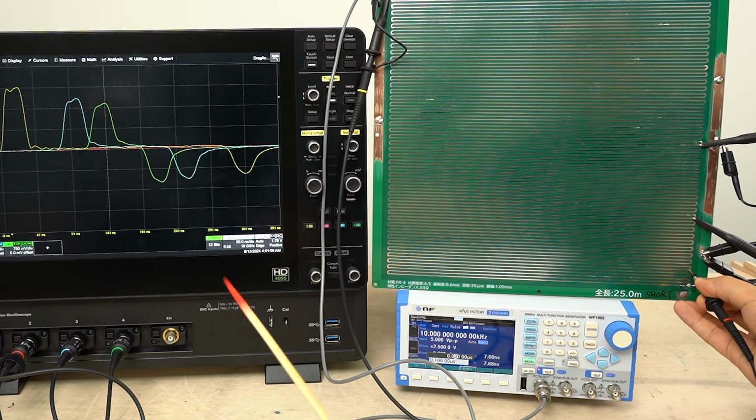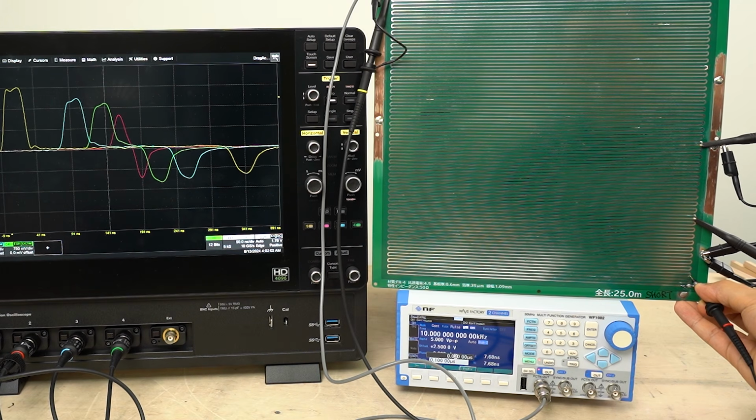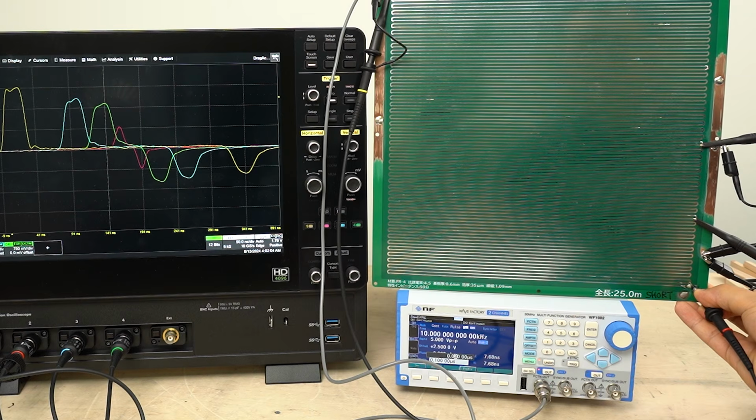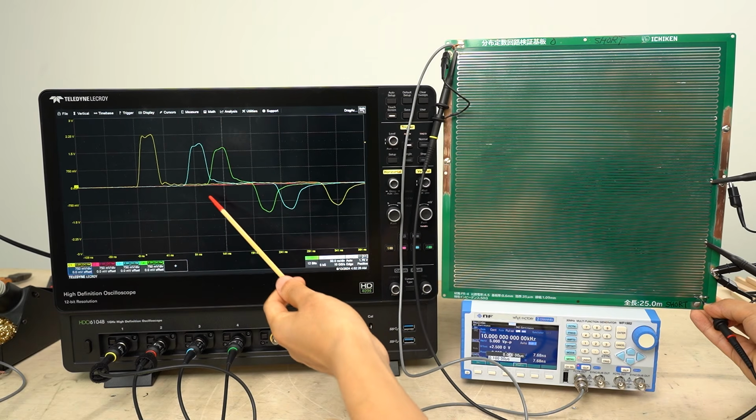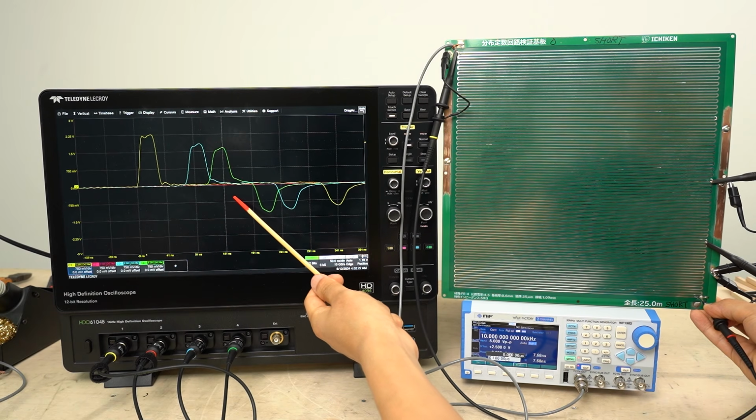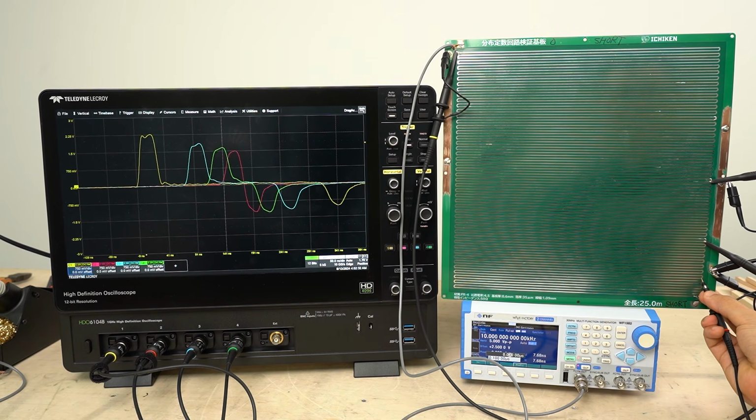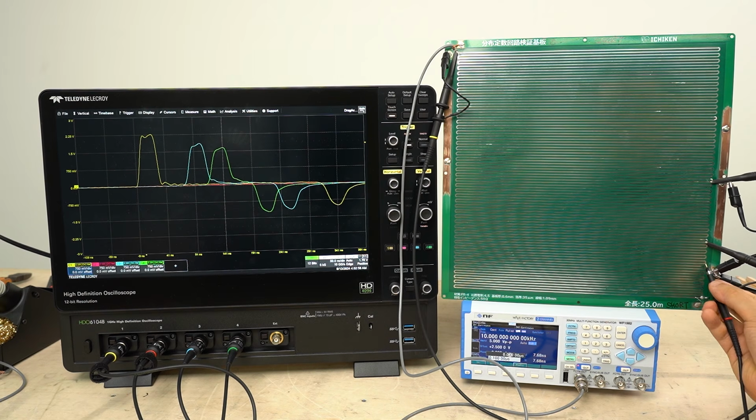The voltage propagates forward like this, and you can see the amplitude starting to drop. As we get closer to the shorted end, it almost looks like the amplitude disappears. And finally, the shorted end. This end is at ground potential. It's directly shorted, so the voltage here is 0. As the voltage travels, the waveform gradually changes, and eventually it drops to 0 at the shorted end.